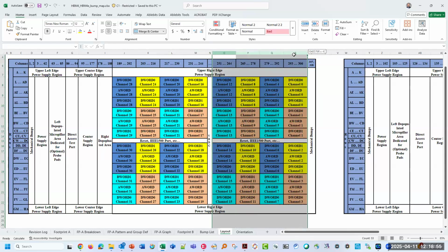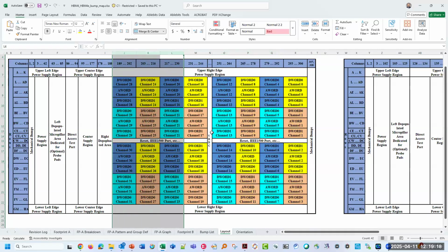So you're thinking in the XML, all of this is the channel that disappears? Well, the other channel technically, because HBM3 goes from 0 to 15. So you'll remove the 16 to 31, and that will get you very close to actual HBM3. Oh, so HBM3 goes this way. In that case, I'd be removing this set. So where does the BDCC move over? I have 5 channels. I don't know off the top of my head, but I think it stays right there. So you still have 4 on this side and 1 on this side.